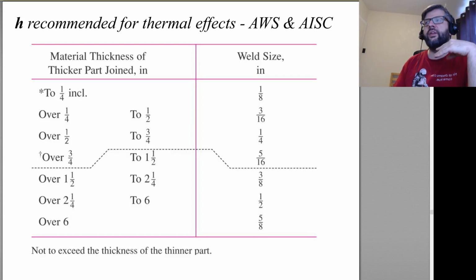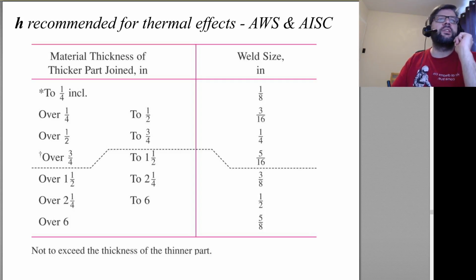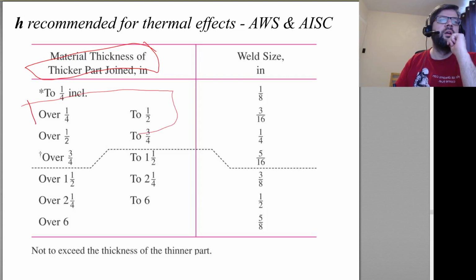So the recommended leg size for your weld, your H value, based upon the thickest of the parts being joined, is given here.